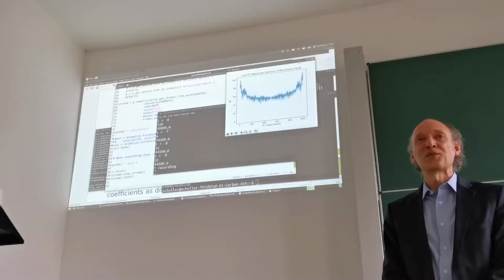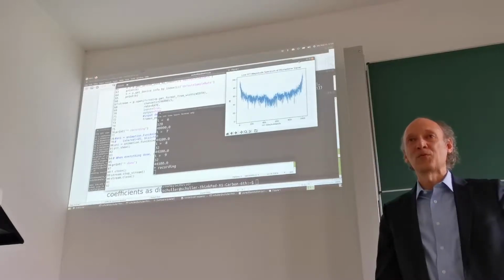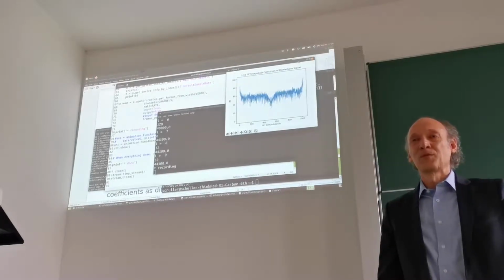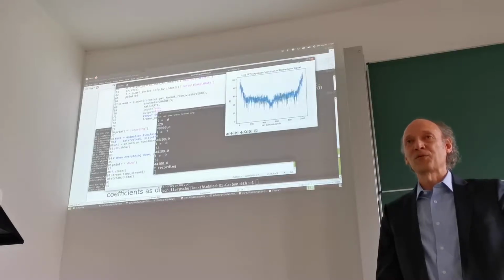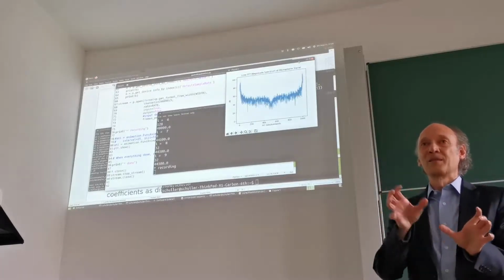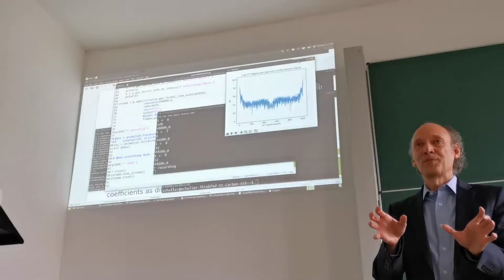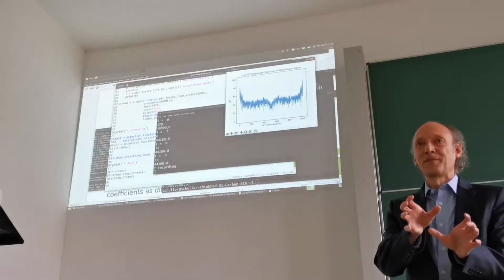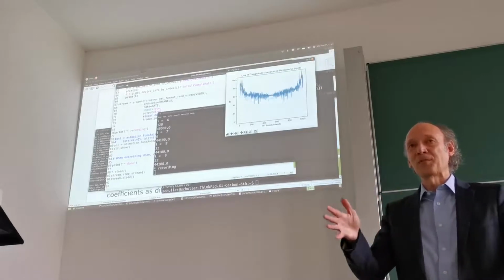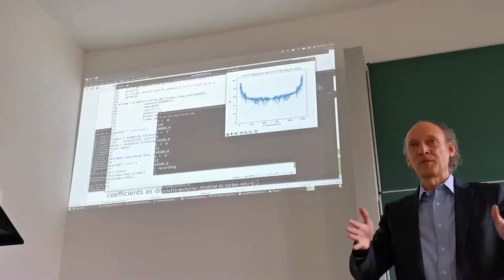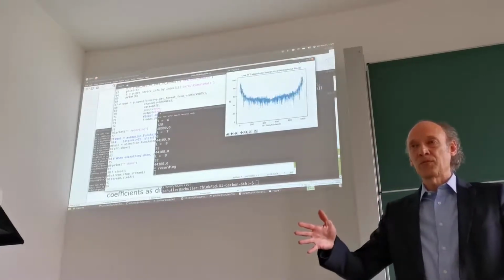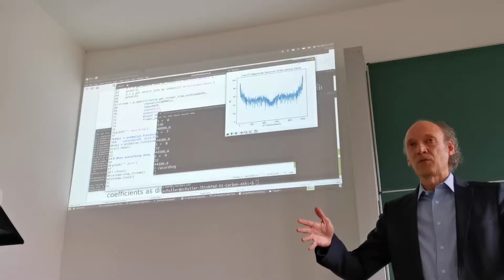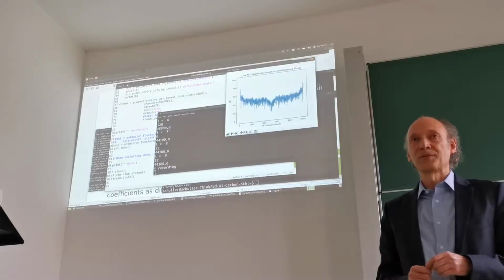The FFT length was 1024. This is how I set it in the program. So if the FFT length is 1024, that means capital N is 1024. And the length is equal to capital N, because that's the number of samples that we deal with. Right? Remember, the number of samples for the FFT was capital N, and this is also called the FFT length.